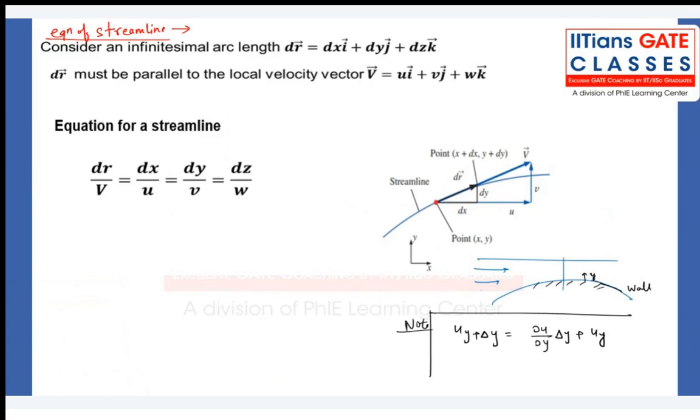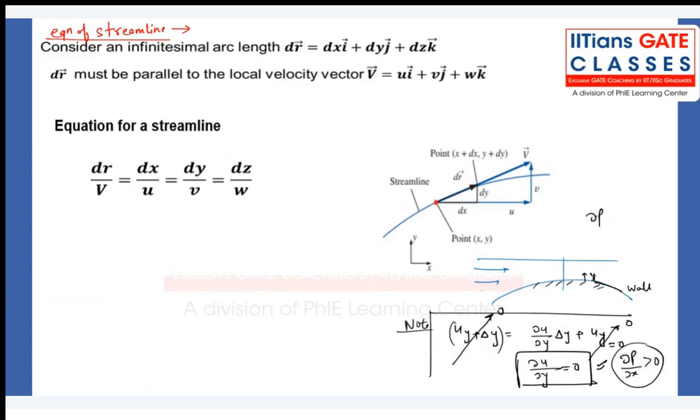Fluid exactly on the surface has to be zero to satisfy the no slip condition. This will be zero at y equal to zero. This has to be zero, right? But what about y plus dy? That also has to be zero for the flow suppression to happen, and that's why you have the condition dou u by dou y, sufficient and necessary conditions, right? Again, this condition will get so much attention when dou p by dou x is greater than zero, right? But only dou p by dou x greater than zero is not a sufficient condition.